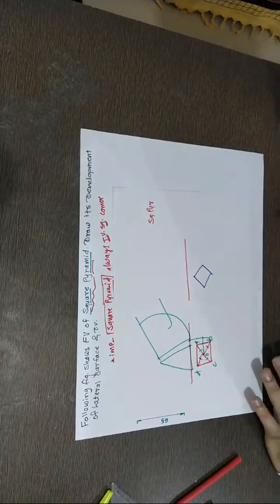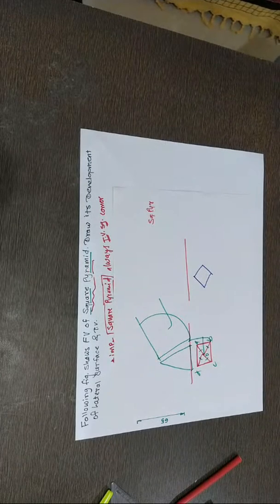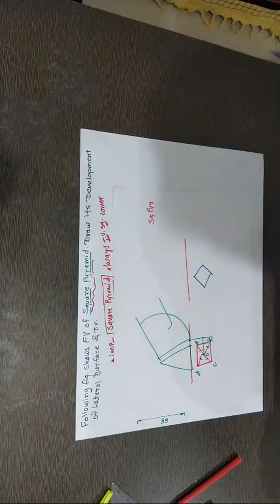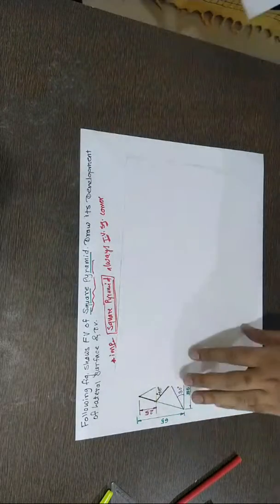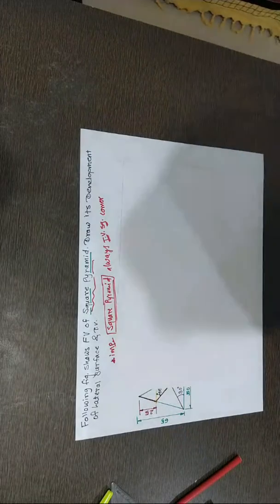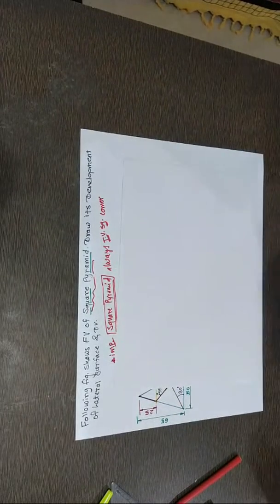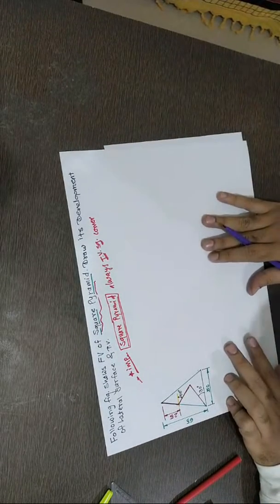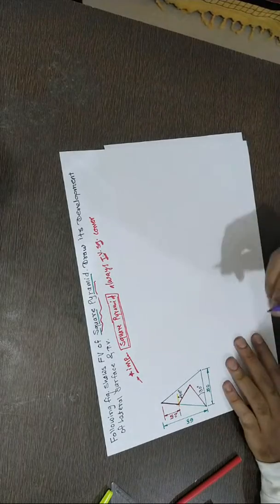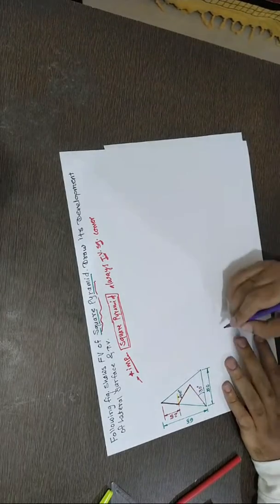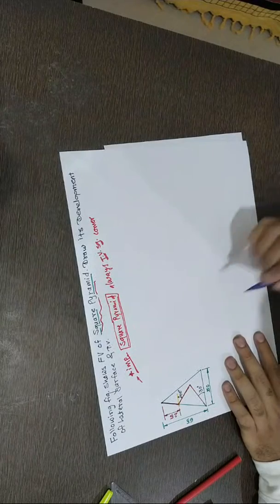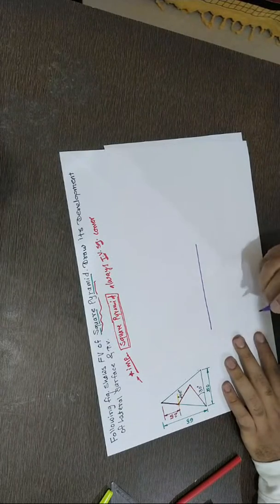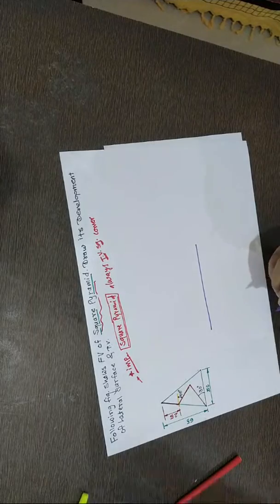Now I'll explain the procedure quickly, so that later you just try on your own and let me know in the comments. Otherwise I'll give you the solution later. So this is the question. I'm not using the main sheet. I'm drawing the top view first. Even though this is the question, I'm starting with the top view first, using rough sketches. I'm not drawing with dimensions. So draw a square resting on a corner. Use a set square. This is a 90-degree angle.